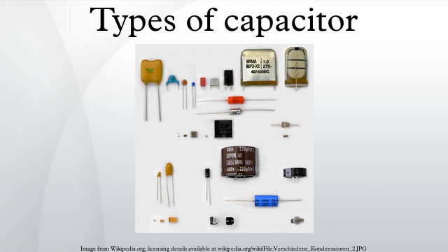Lightning strikes and other sources cause high voltage surges in mains power. Safety capacitors protect humans and devices from high voltage surges by shunting the surge energy to ground. In particular, safety regulations mandate a particular arrangement of Class X and Class Y mains filtering capacitors.